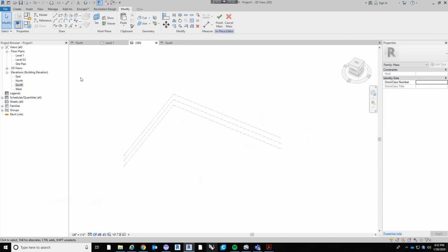In Revit's conceptual mass, if you want to revolve a specific geometry, the axis has to be a reference line. Reference planes and reference lines are different. Reference planes are unending planes. Lines are just line work, but they have a little bit more importance.